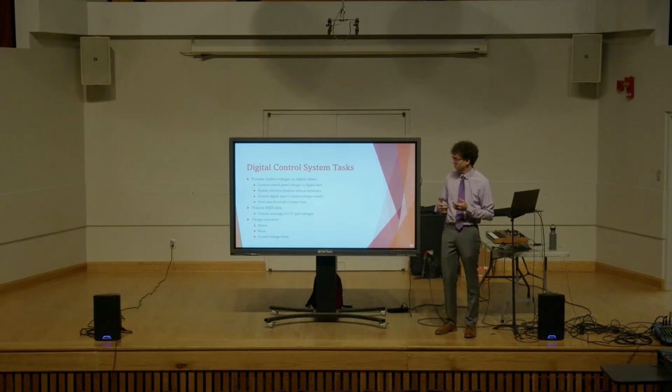And that information will have to update in real time as necessary. So say you load a preset, but then you tweak a knob, that knob tweak should be reflected in the sound that you're hearing. You'll have to convert the digital data to control voltage outputs, which is possible through a digital to analog converter, which I'll show you in a short moment. And then you have to be able to store data for recall at a later time, which again isn't terribly hard once you have that data as digital data.